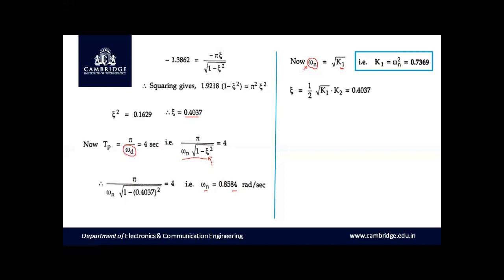Similarly, we know that zeta is equal to 1 by 2 into square root of k1 into k2. This is the expression which we have compared with the standard characteristic equation and we have obtained this in the beginning. Now we know that zeta is equal to 0.4037. So let us substitute for zeta here in this expression and we have obtained the value of k1 as 0.7369 just now. Let us substitute for k1 in this expression. So we can obtain the value of k2. For the simplification, we obtain the value of k2 as 0.9403.